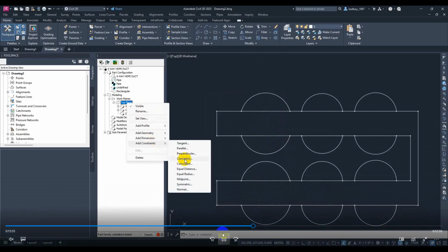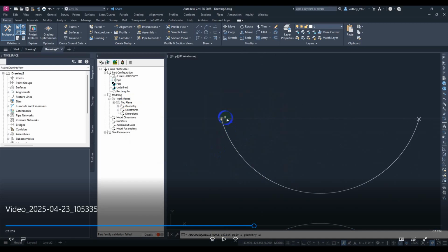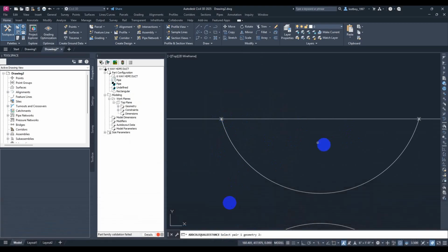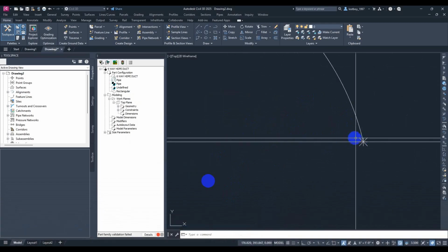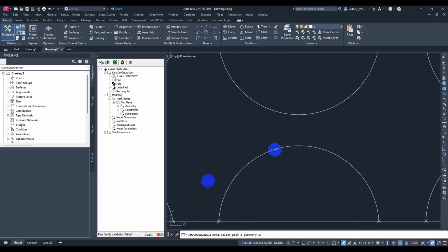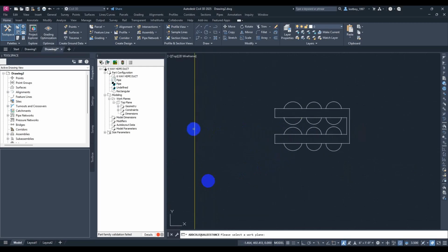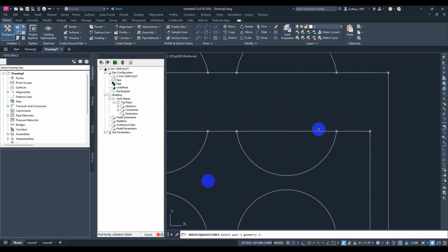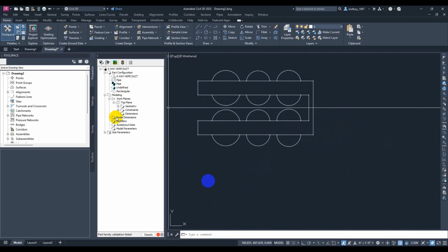So what we will do, we will be adding equal distance constraint between the upper pipe and the lower pipe, as the ones that we have missed before, that I told you. We will adding a constraint of equal distance now. Yes. Also here, now I made sure that all the below circles are equal to the upper circles. And when I change some dimension upper, it will affecting all the points below. So they all will align on the same vertical line.